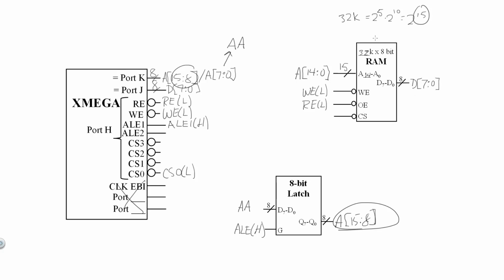And the chip select that's going to enable the SRAM is going to be directly related to the chip select that we've defined with the EBI. So now anytime I write to an address in this range, 8000 to FFFF, the chip select will go true, which will enable the SRAM, and then depending on if it's a read or a write from the processor, the respective action will happen.